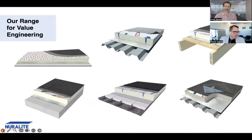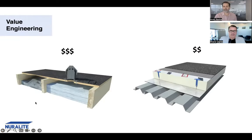So yeah, and in terms of the thermal performance of the roof, the warm roof is more effective in terms of long-term energy efficiency, reducing the cost to heat and cool the building. Because we don't have the thermal bridging that you have with a cold roof, then it's long term. Definitely there's savings to be made there.